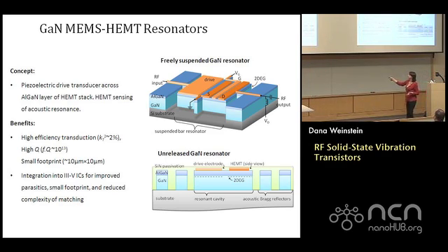So if I have a transistor running through this, I have heating in the device. That heating is going to affect the transistor performance. It's also going to affect the temperature of my resonator in terms of frequency, right? So if I can dissipate heat, I can have linearity over a much larger power range, right? Which is important for filters.